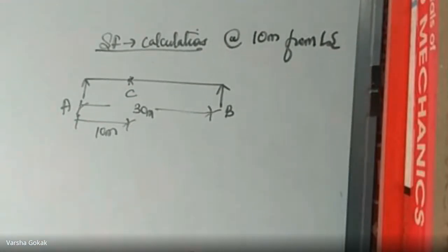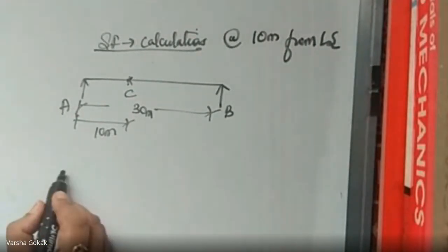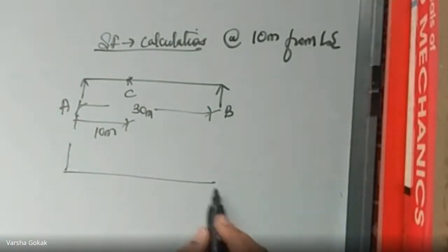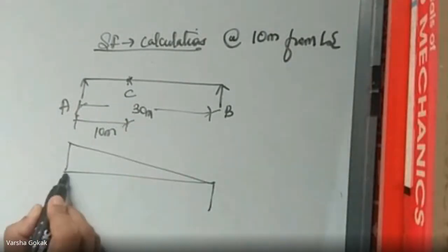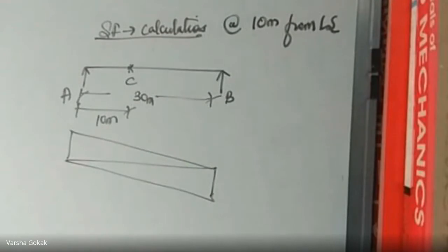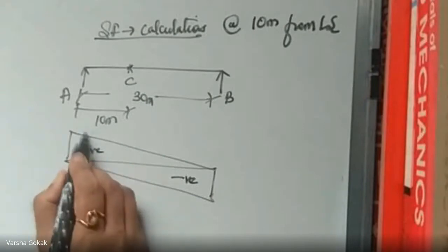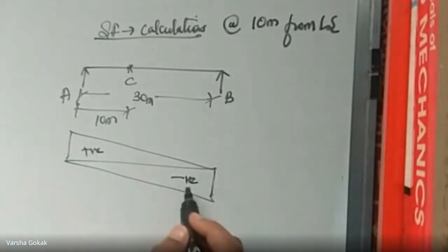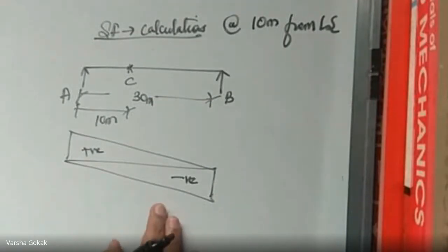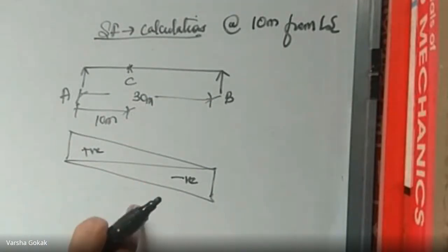We know the pattern of the shear force diagram when we draw the ILD. It is something like this. For all the examples, we have taken the shear force. This is your negative, this is going to be your positive. Then we mark the positive and negative ordinates and we multiply. So it is the same thing now, but the change is where to place the loading.